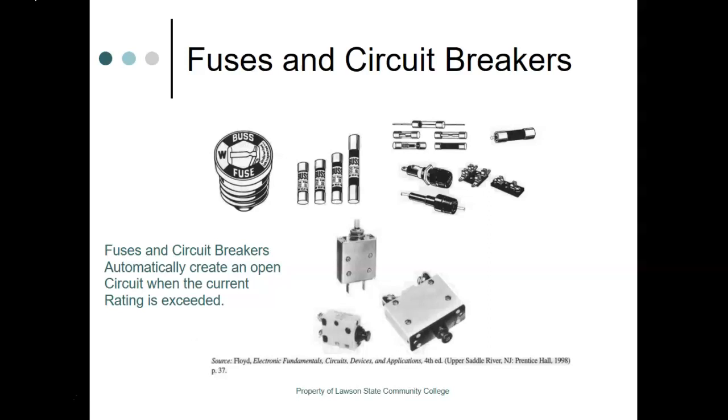But they try to look at the wire rating and put that circuit breaker right at that wire rating. Why? Because you want the circuit breaker to give up before the wire does. That's just the fact of the matter. That's why we don't use fuses anymore. A bigger fuse does not mean you get to keep everything. It just means you created a ticking time bomb in your house.